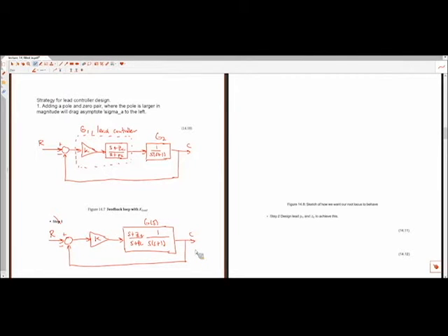So just as a quick aside, this is more mathematical, that we're lumping these together. Keep in mind, G2 represents the plant. So this would be something physical, something you can sit at your desk or in a manufacturing facility, wherever you are. So we're mathematically lumping this with the compensator or controller, which is the dynamic portion of the lead controller, which is usually something in software. So we're mathematically lumping something that's virtual and physical, but keep in mind that hardware-wise these are two completely different entities.